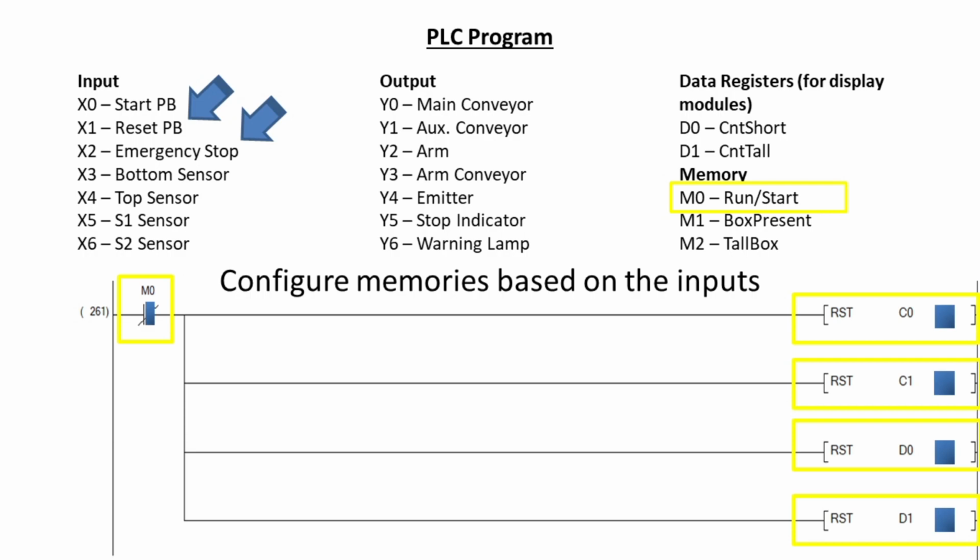Moving on to the task of displaying these saved counter values, the steps are as follows. Choose a numerical display that matches your PLC specifications. Evaluate the communication protocol supported by your PLC and the chosen numerical display. Establish a connection by using appropriate communication cables to link the PLC and the designated display. Configure the PLC to send the values from D0 and D1 to the selected displays. This ensures that the counter values are accurately conveyed and displayed on the numerical interface.